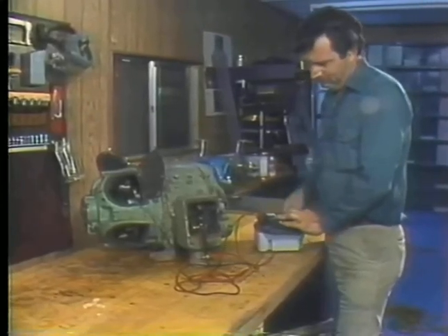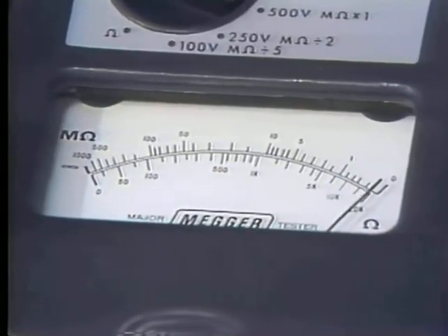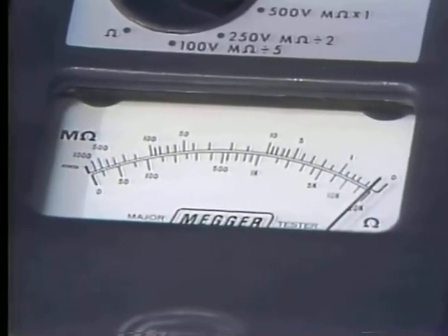All right, let's check. Well, this motor is grounded. If all you had to do was report whether or not the motor was grounded, you could say yes and be done. But if you had to repair it, then you'd have to locate the grounded part or parts. There's no guarantee there's only one. Here's where you use the process of elimination to save you time and prevent unnecessary confusion and error.